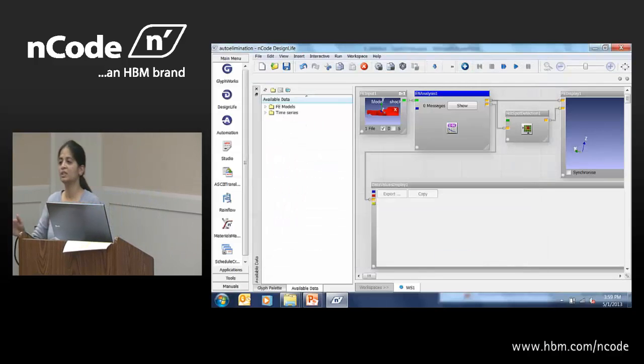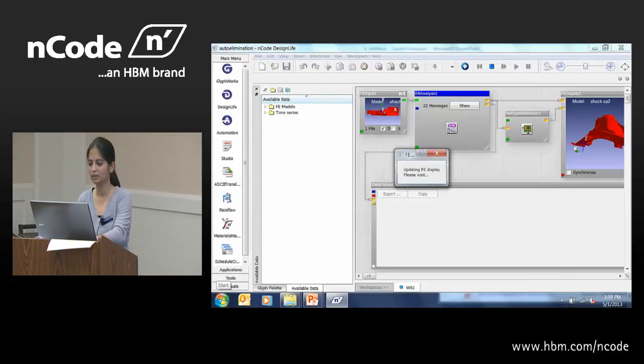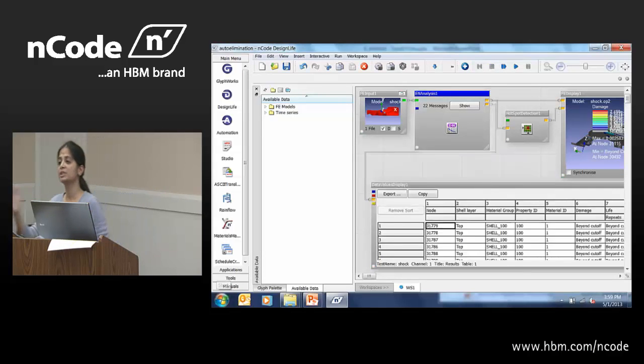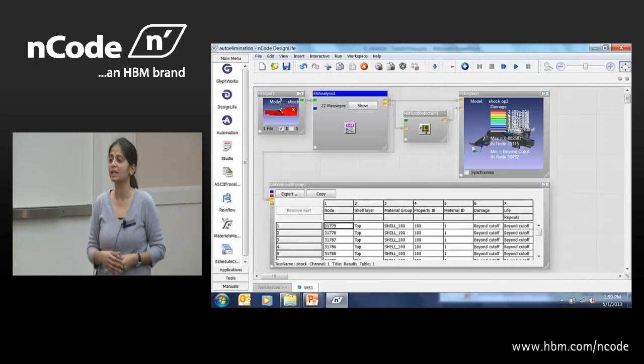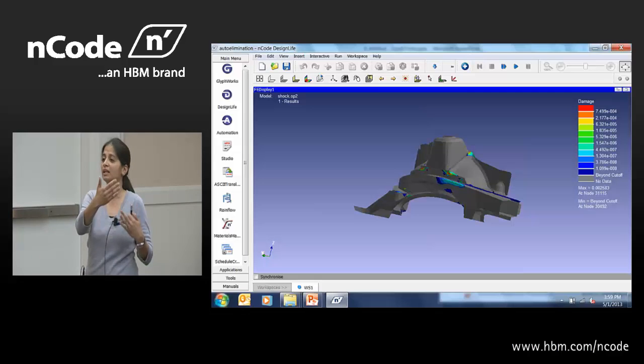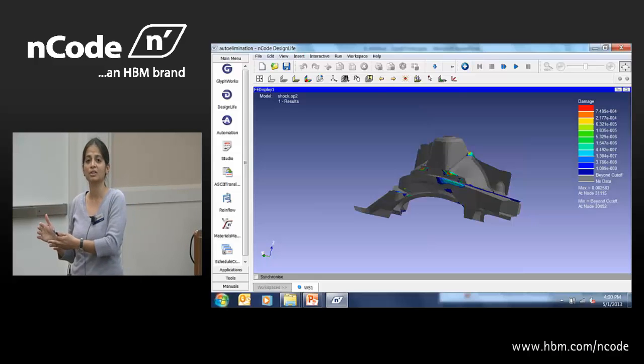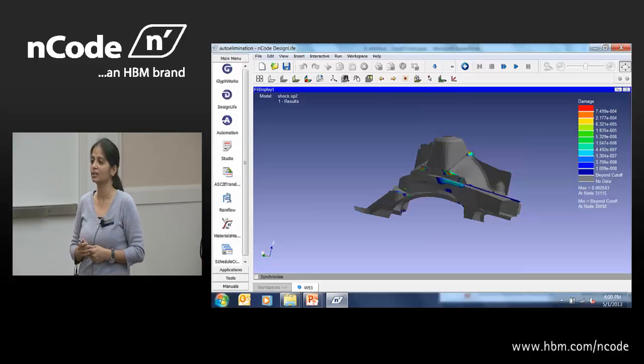You'll notice that when it finishes running, it writes out results only for 10% of my model, or whatever percentage I specify. You can use the wizard to build a stress-based filter, a damage-based filter, and as many filter runs as you want. The idea is to cut down the model that you give the software for the final detailed damage calculation.